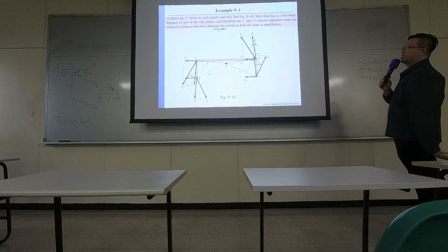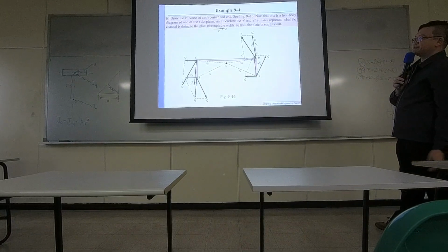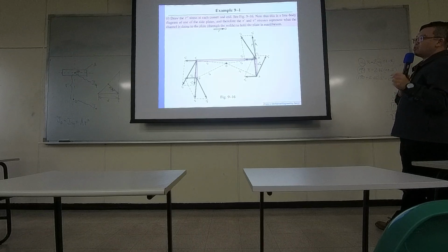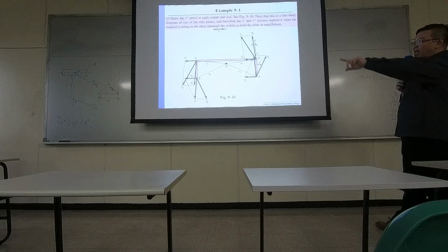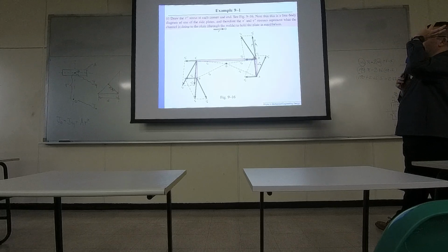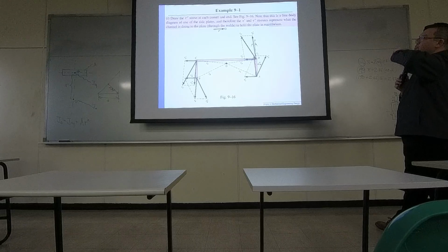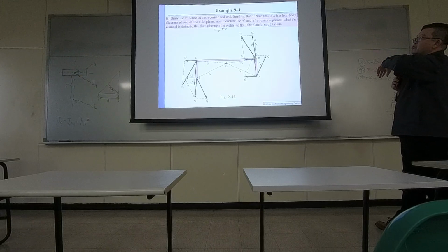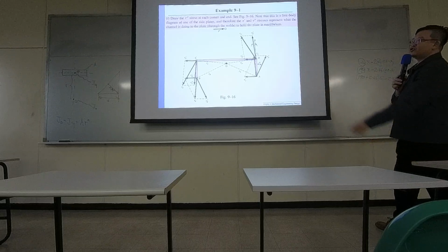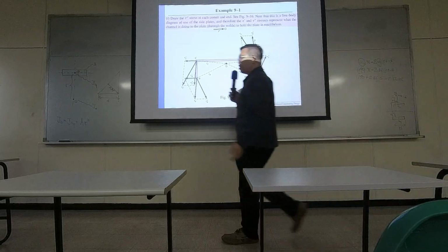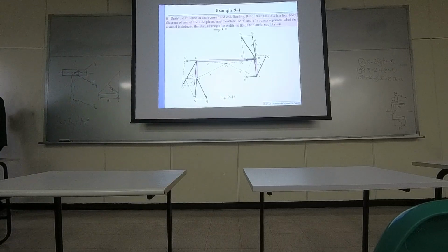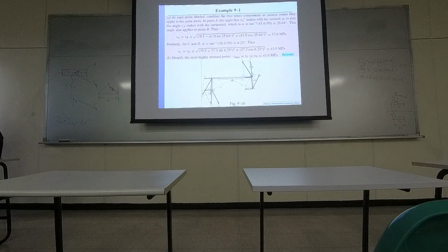So overall, at four different corners, their normal shear is the same, which is going left horizontally, but their rotational shear is pointing in different directions. What you need to do next is to compute the overall shear at all four positions, and then you will figure out which point has the largest overall shear. So the book already did the math for us. At the end, points C and D have greater shearing stress.